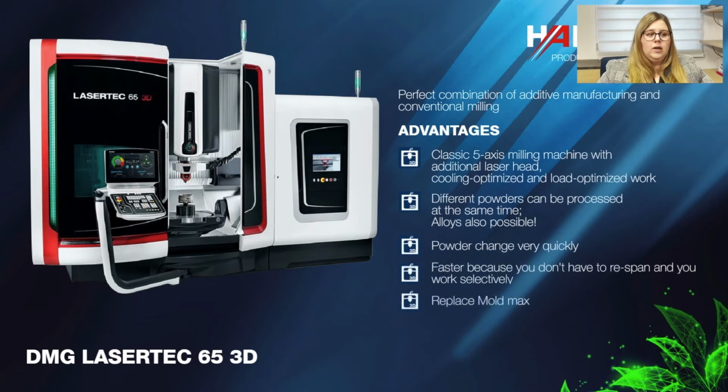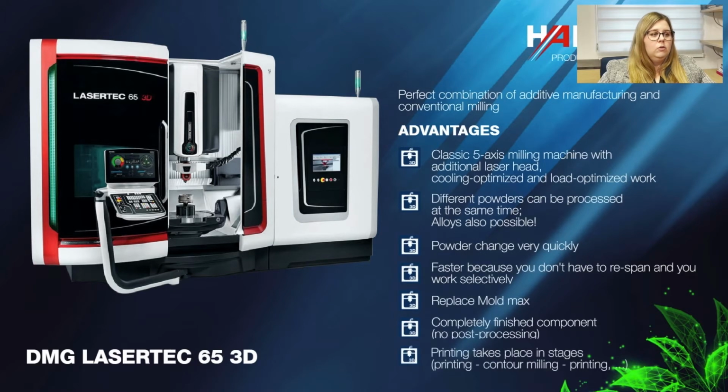Now, those were the conventional 3D printers. I would now like to present our hybrid machine, the LaserTech TT. This machine combines a classic 5-axis milling machine with an additional laser head, so that's additive manufacturing. And this provides different advantages. So we can work in a cooling optimized and load optimized way, and different powders can be processed at the same time. And this not only saves time because you can work with two powders at the same time, but it's also possible to create alloys.